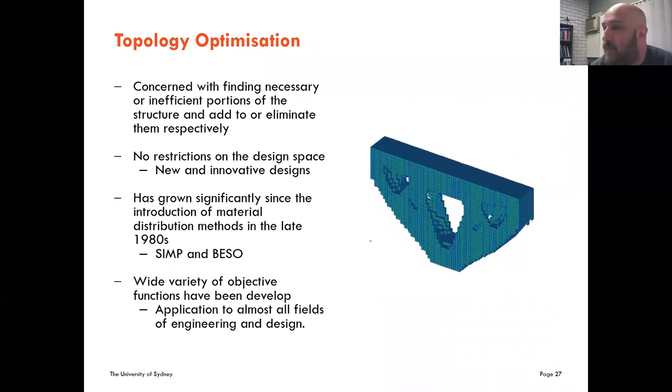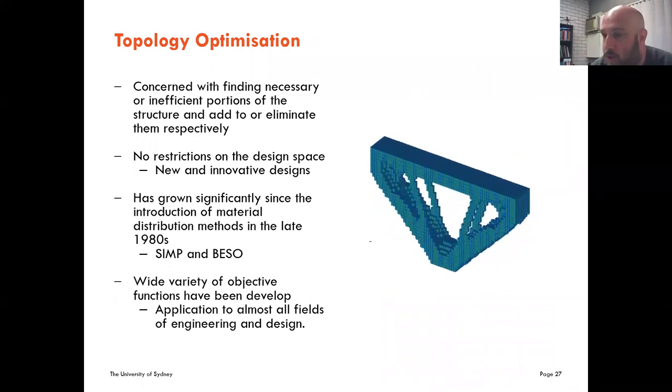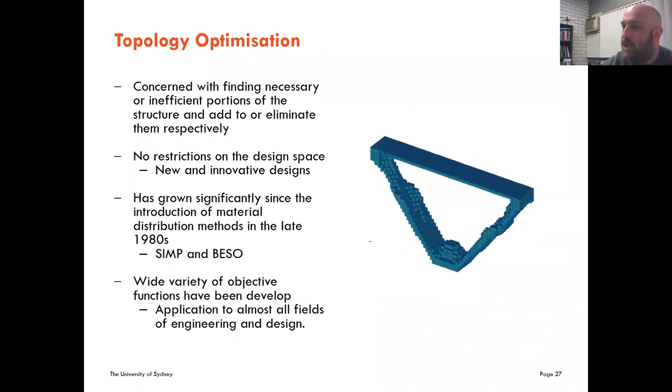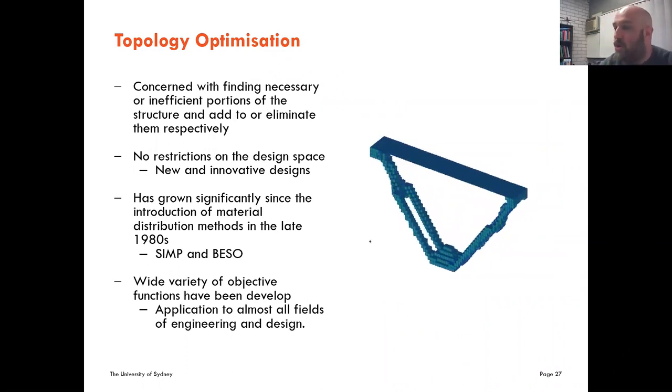Okay, so what I'm going to talk about now is probably a little bit more of the oddball part, which is topology optimization. So you're seeing a video of what topology optimization is. With topology optimization, you start with a predefined domain, and you slowly remove or add bits and pieces until you end up with a structure that is compliant with whatever constraints you want.